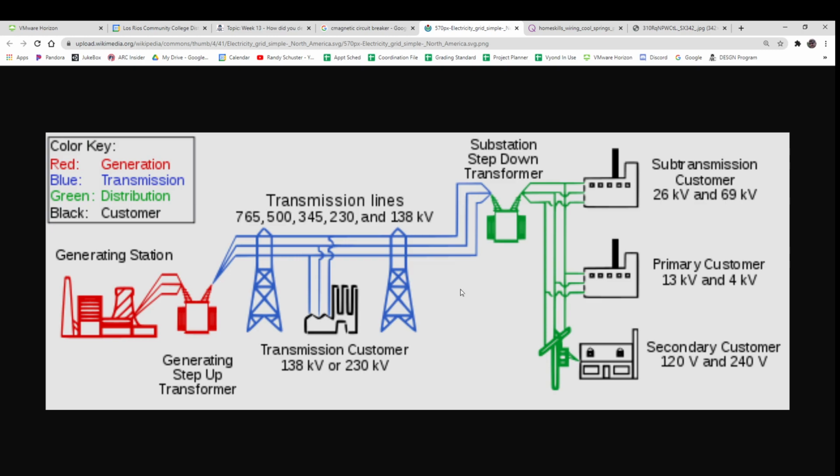Yeah, well, depending on which set of wires it was, what it means was that your circuit breaker either malfunctioned, which is really bad news, or the circuit breaker was sized too large for what was on the circuit.